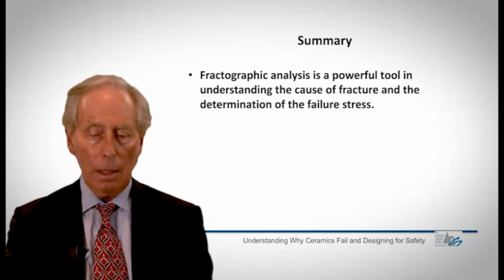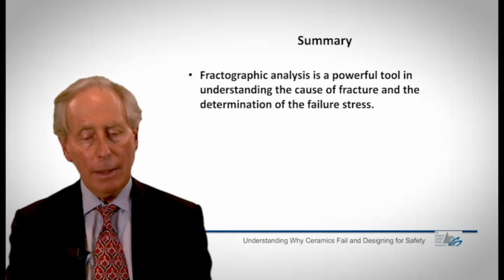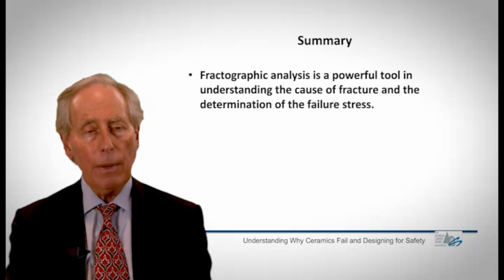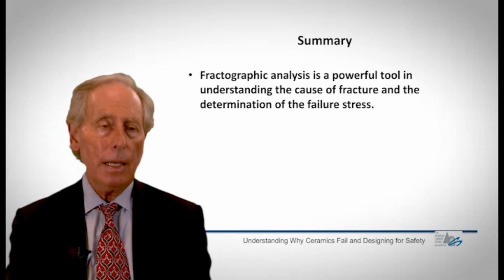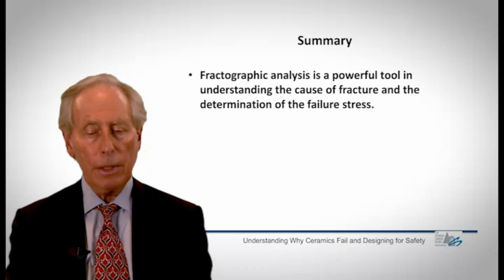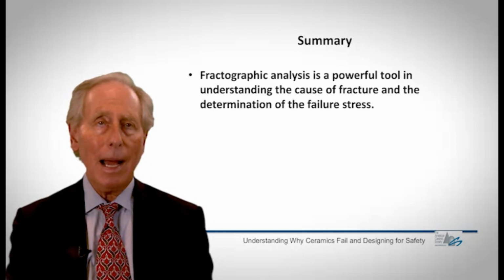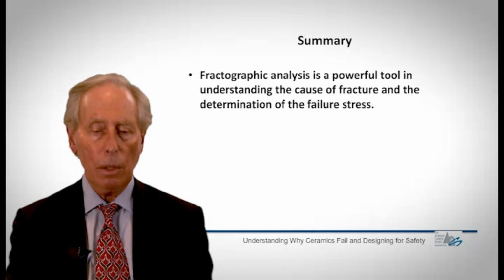So summarizing, I think there was only one short message: it's a powerful tool to understand the cause of fracture and the determination of the fracture stress. I spoke earlier about the need to do fractographic analysis to determine the cause of failure, whether it's an inclusion, a different shape flaw, a different size flaw, in order to understand the statistical nature of the failure origins. But it can tell you a lot more. It's much more quantitative in nature, and so gives you a lot better information about the stresses in the material and some guidance as to whether there was a problem with the material or an overstress due to some phenomenon that you were not predicting.